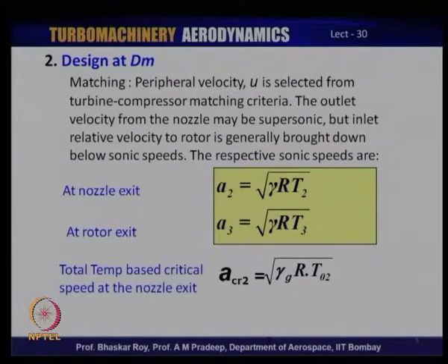Normally, they are not supersonic rotors even today, because of the need for cooling that needs to be embedded in the turbine blade shape. However, it is possible that in future some of the blades would go supersonic, where cooling technology would be appropriately used or eliminated.